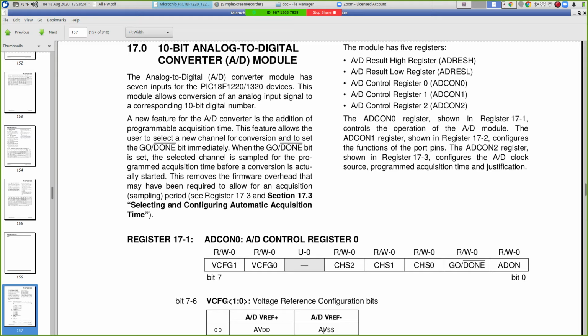If you want to have a variable resistor, a potentiometer, so you can have a digital volume knob, right? At one end it'll be 0 volts, at the other end it'll be 5 volts. Well, you would have 1,000 spaces in between, off and on, that you could discriminate between. And you'd pick up each change of 5 millivolts in the input voltage.